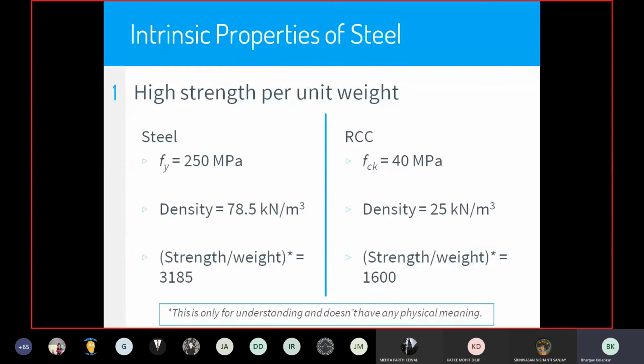If instead of a 500 by 500 concrete column, you can use an ISMB 400 steel section, we will look at what ISMB 400 is, but it is smaller than a 500 by 500 concrete section. You will always go for an ISMB 400 section if other conditions permit, because that gives you a larger carpet area. Smaller the size of sections, smaller would be the size of foundation and lesser would be the cost of foundation.